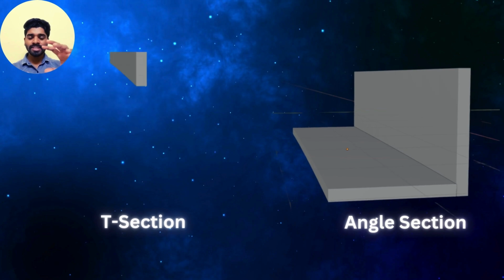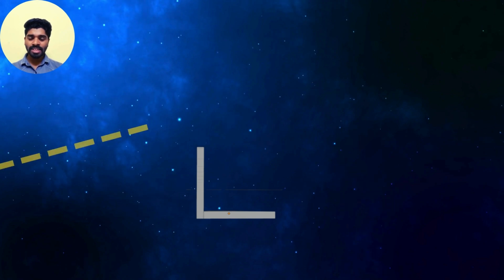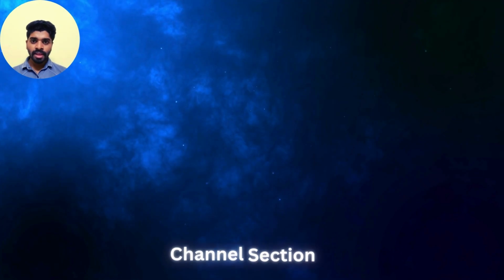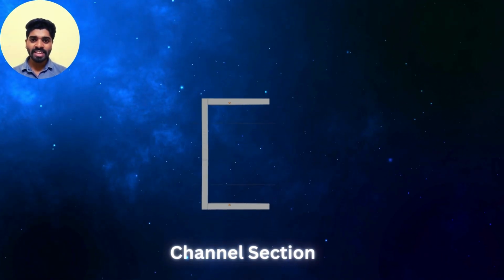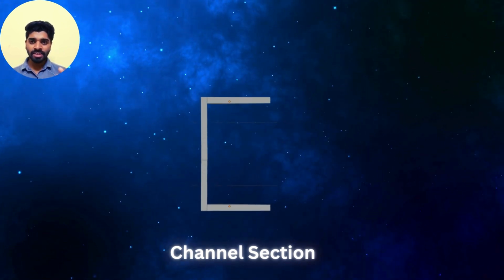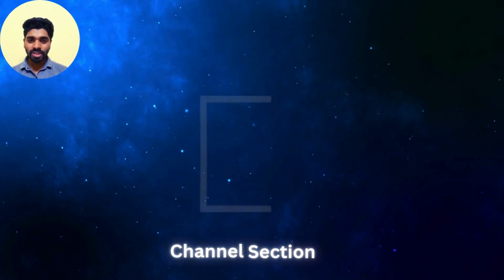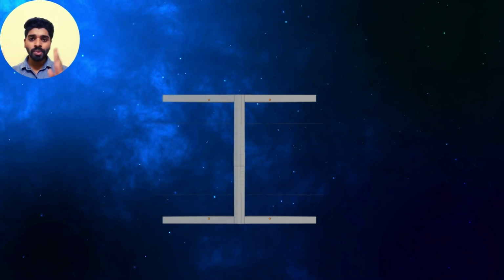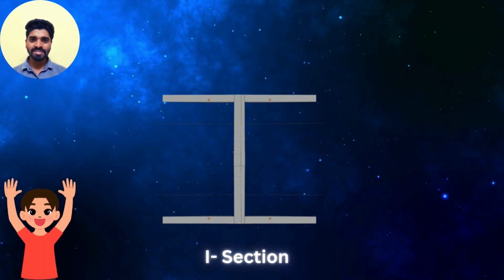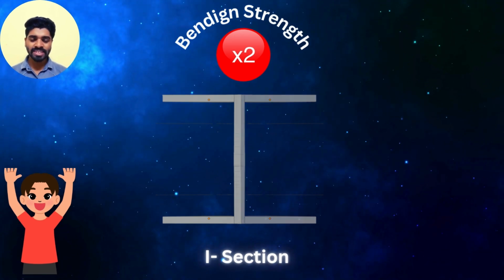Now if we take the angle section as a unit section, then if we want to increase the capacity of this section further, we can attach one more angle section by mirroring it. So now it becomes our channel section. If we want to increase our bending strength in both directions, then we can use this section. Now if you want to further increase its bending strength in both axes, then you can attach one more channel section to the back side of this. So overall it will become an I section. Now this I section will have nearly double the bending strength in both axes.